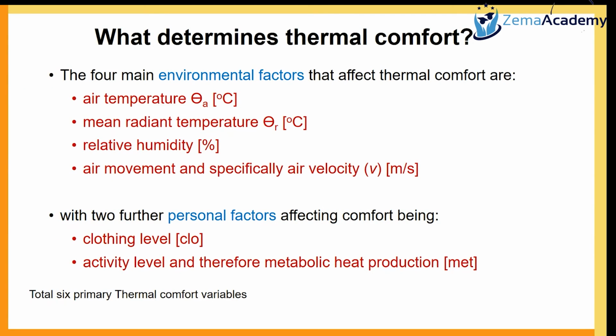However, there may be situations where the introduction of air is at a higher rate with a higher velocity. So the person sitting at the point where this introduction and extraction is taking place may feel localized discomfort. Okay, so looking at air movement and specifically air velocity is also important in order to define thermal comfort from the point of view of occupants.